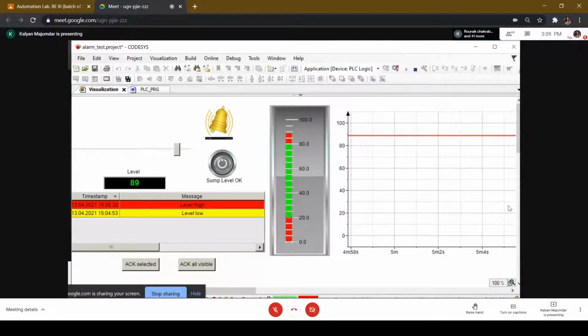As I said, in the controller that PD discussed, the responsibility of developing the alarms was yours. You wrote the software to develop those particular alarms. The alarms were, one, that there was no water in the sump. The second alarm was overload condition is true, and the third alarm was that the tank did not fill up within a certain amount of time.